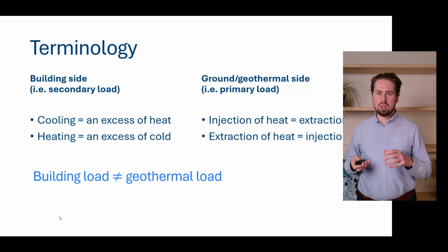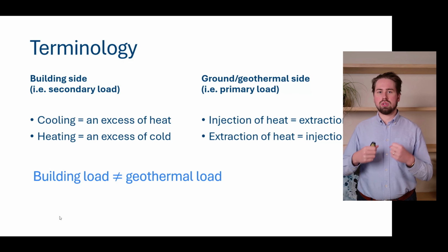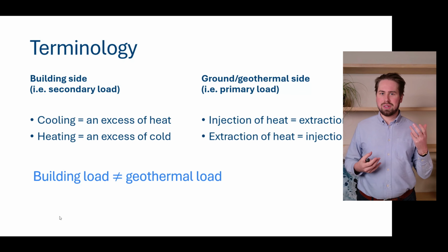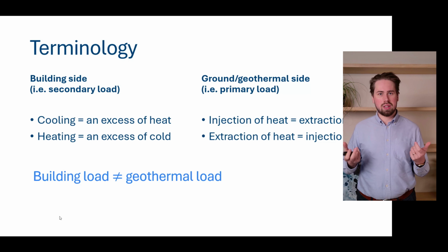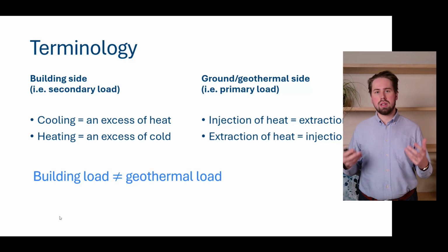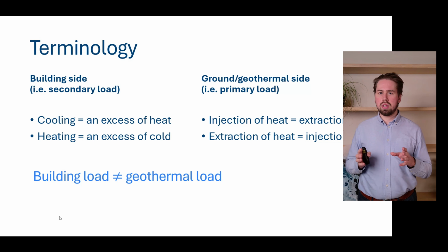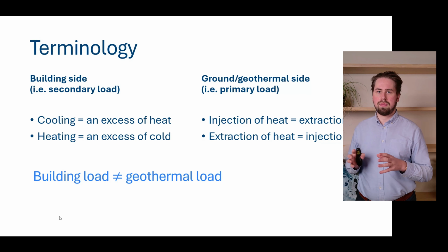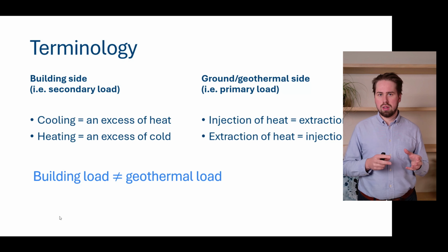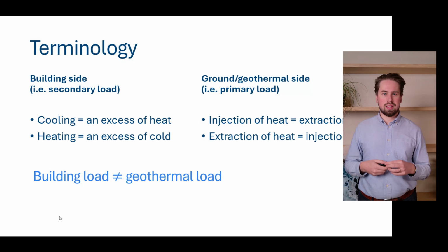And of course, there is a link between, for example, heating, where you extract a certain amount of energy from the ground to heat your building, but your kilowatt hours in heating are not the same kilowatt hours as extraction, because there is a heat pump in between. And if you're not careful about terminology when you're talking about ground loads and building loads, you may end up with a wrong design in the end. So in GHG2 you can either work with the building demands or with the ground loads themselves. Now typically you work with the building demands, or you have to estimate some building demand first, which is what we will be doing in this lecture.